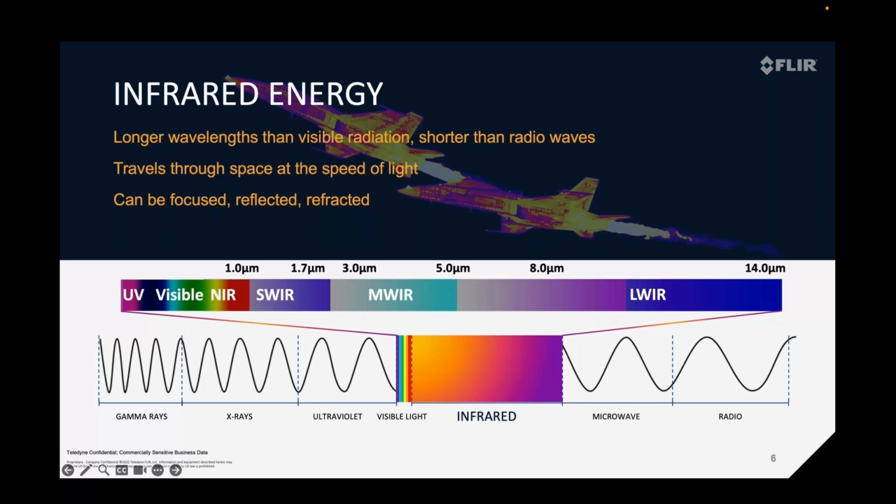Higher-end infrared cameras also can run in this band, and they use cooled detectors made from strain layer superlattice or SLS material. You'll also see MCT in this band. SLS long wave has benefits including broader thermal ranges, short integration times, and for those interested in spectral measurements, it has long wave response.